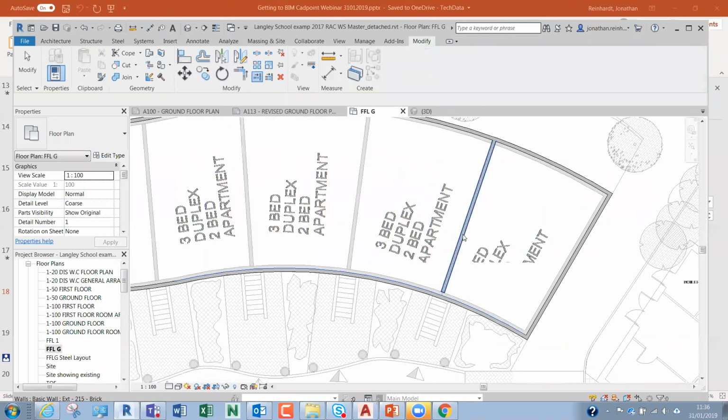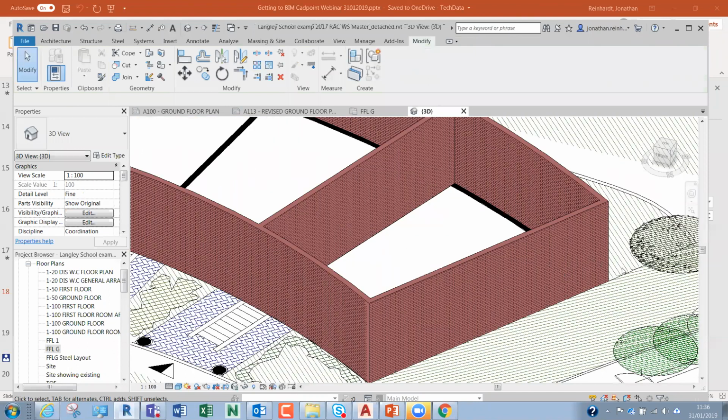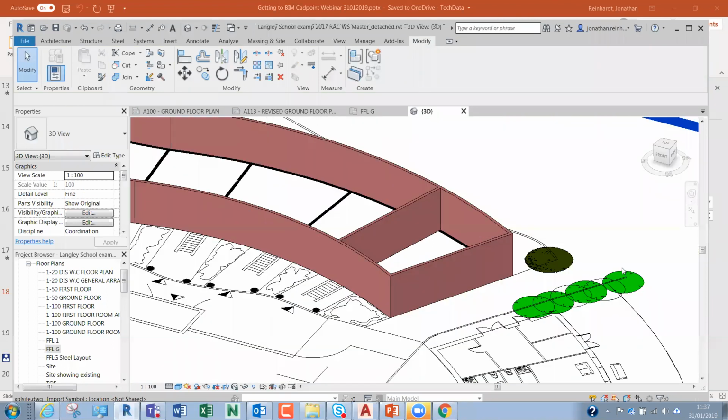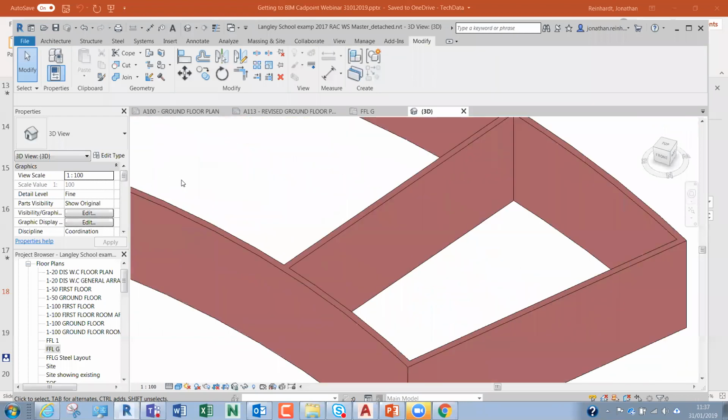So you can see I've started to create a 3D model already, completely navigated in a 3D space, being able to see it in the real world space just almost in a matter of seconds. So I can also just turn off that as well. I'm just going to type in something here called EH, or element hide, which you can do from your keyboard if you wish. So I've started to create some walls, and as I said, look, we're not going to have that wall construction in between our two apartments or whatever this building design is.